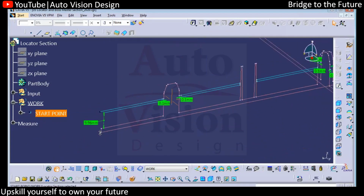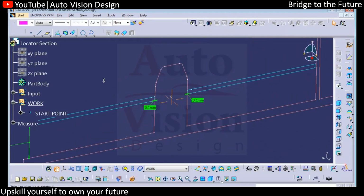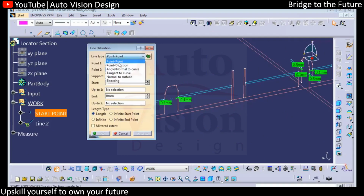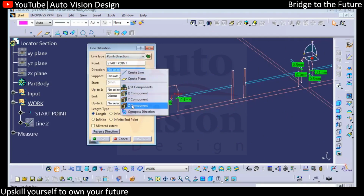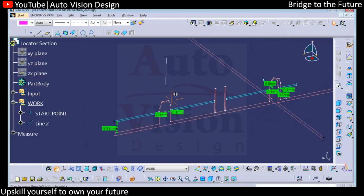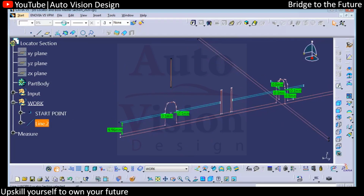Then we need to create a sketch. With respect to this we need to have the tooling lines. We'll add the tooling line. So this we can add direction as Z. Somewhere in this direction we can add it, and this we can name as a tooling line. So this we can go for just as a tooling line.